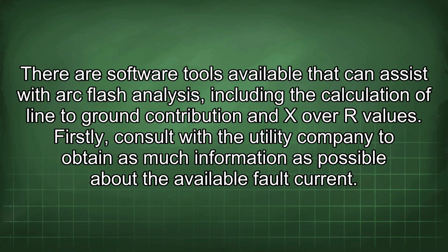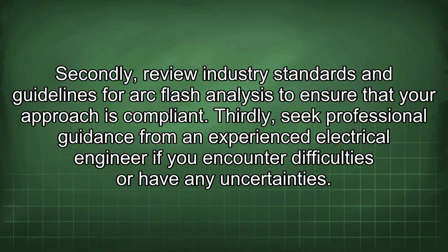There are software tools available that can assist with arc flash analysis, including the calculation of line-to-ground contribution and X over R values. Firstly, consult with the utility company to obtain as much information as possible about the available fault current. Secondly, review industry standards and guidelines for arc flash analysis to ensure that your approach is compliant. Thirdly, seek professional guidance from an experienced electrical engineer if you encounter difficulties or have any uncertainties.